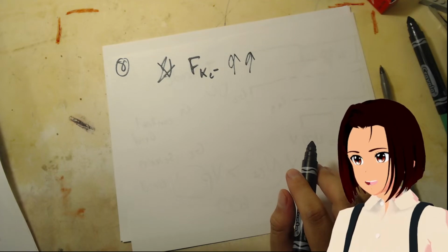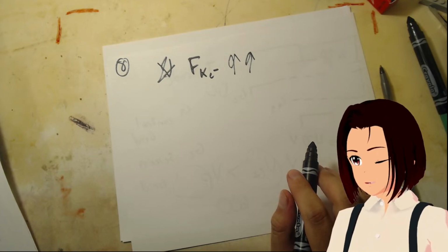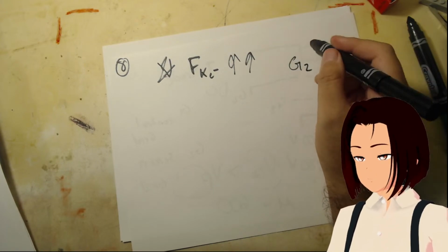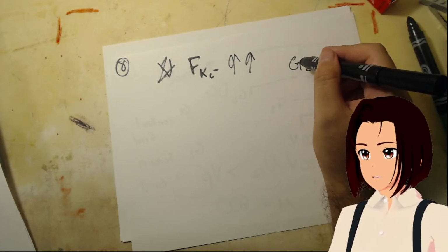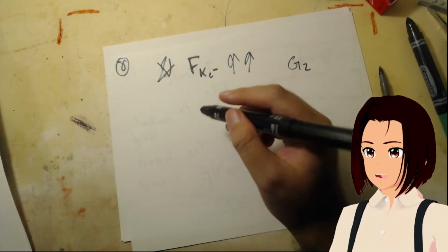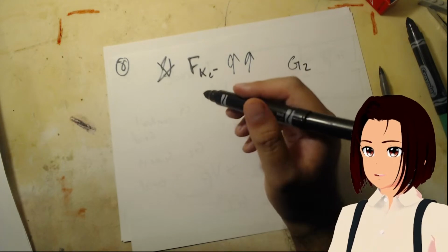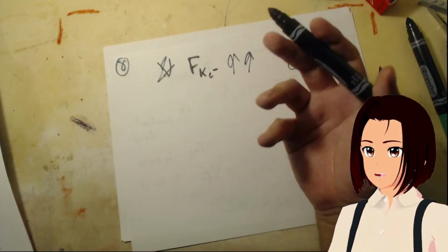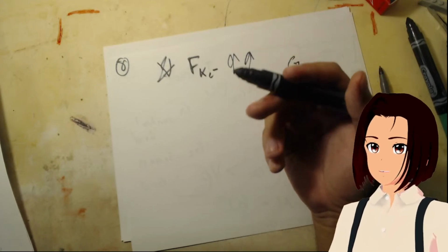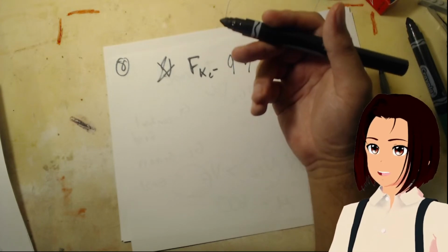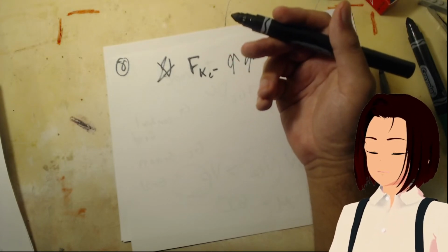When you get electrons knocking off, some of them are going to be at the screen grid. We want electrons to go to the plate, but some are going to go to the screen grid. So we're going to have current flowing in the opposite direction of where we want it to go.